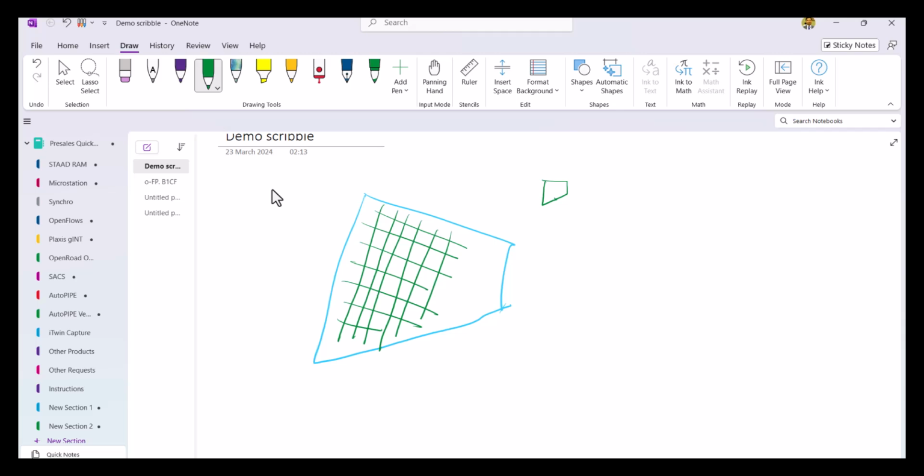So what you need to do is draw a line like this and find out what would be the total moment about this line, and use the respective moment for calculating the reinforcement needed to tackle those forces. Now, there are two different approaches. You can take total forces, or you can split them into different zones and use the forces for that particular zone.